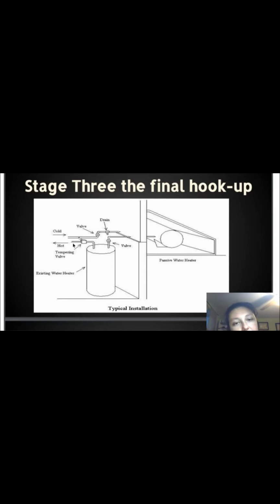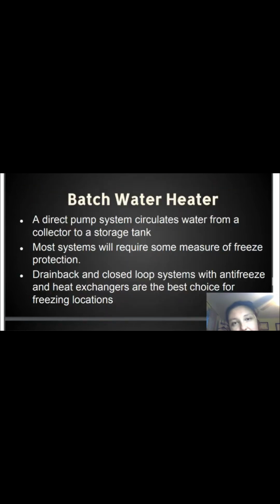So now every time I'm pulling water from here and I need to refill, this is pulling water from this tank. And as this tank gets empty, it's pulling water from the actual cold line. So I'm constantly heating it up, maybe up to 100 degrees, and then I'm only heating it up another 20, right? So 55, heating it up 45 degrees, coming in here at 100, set to 120, 20 more degrees, out the line. A lot less energy utilized in this sort of build.